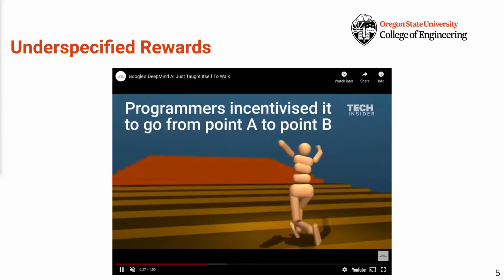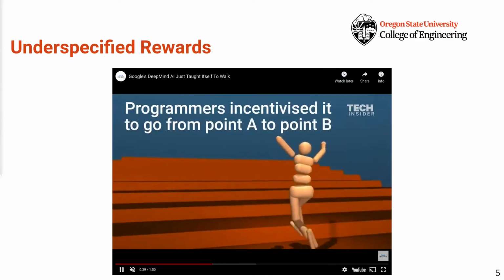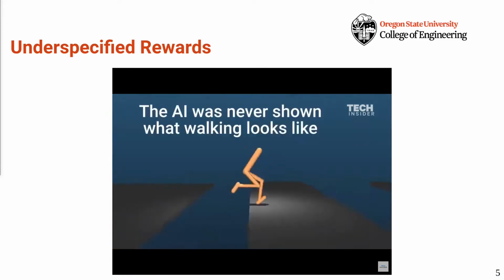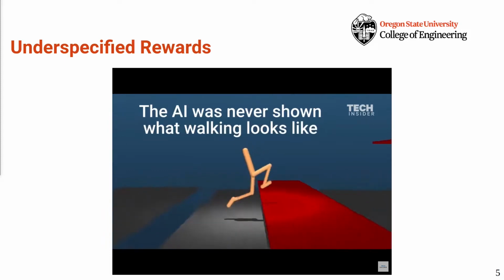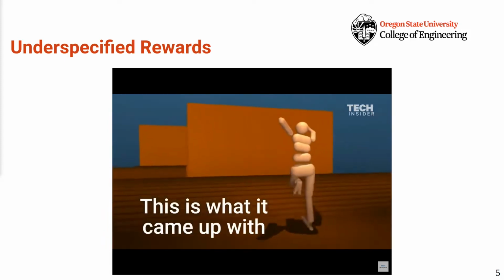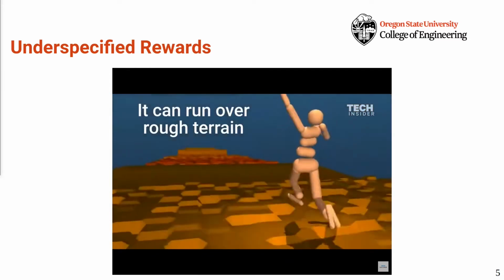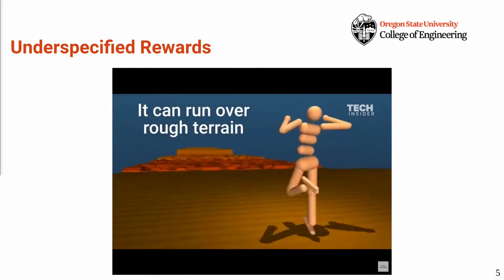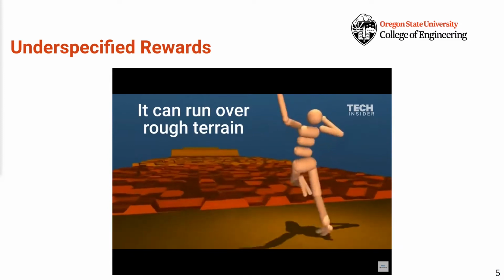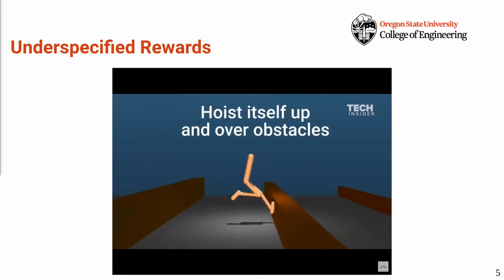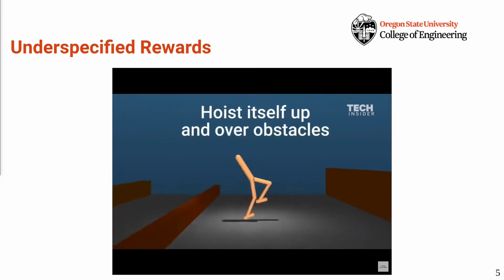On the other hand, clearly, some sort of reward structure is obviously necessary. The type of reward function used in the policies shown in this video won't work on hardware because it is too underspecified. In addition, by using such a simple reward specification, there is no way to command a particular type of desired gait, such as running instead of walking. So, how do we write a reward function for bipedal locomotion which is neither overconstrained nor underspecified?